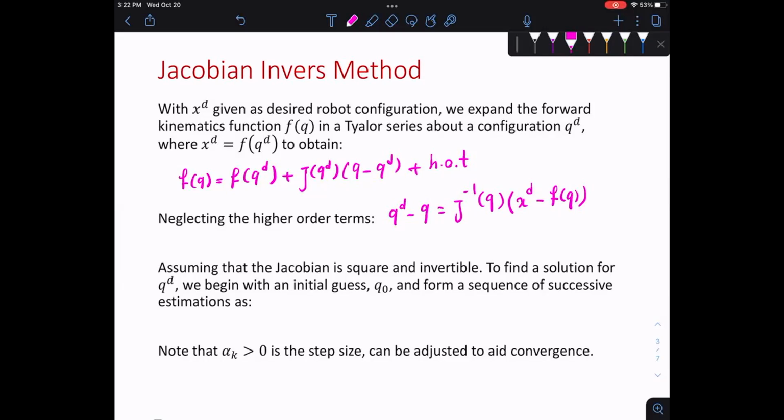So there should now be a different guess. We can usually use some steps, right? You can define a constant value for it. You can define it as a function of k, or it could be a matrix where you use a diagonal, like weights. If you're dealing with a robot, maybe theta 1 is more important, has more weight, because whenever theta 1 moves, it moves the end effector, because it moves both links. So theta 1 actually moves joint 2 too. So theta 1 should have more weight if you're thinking of using a covariance matrix, right?